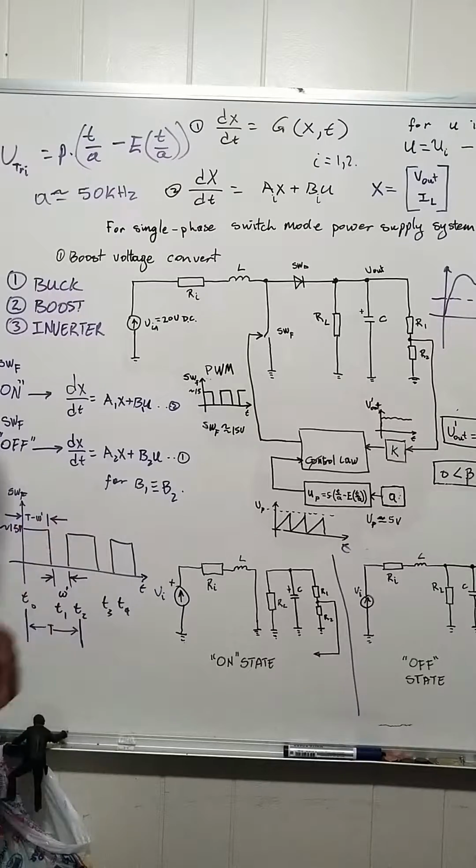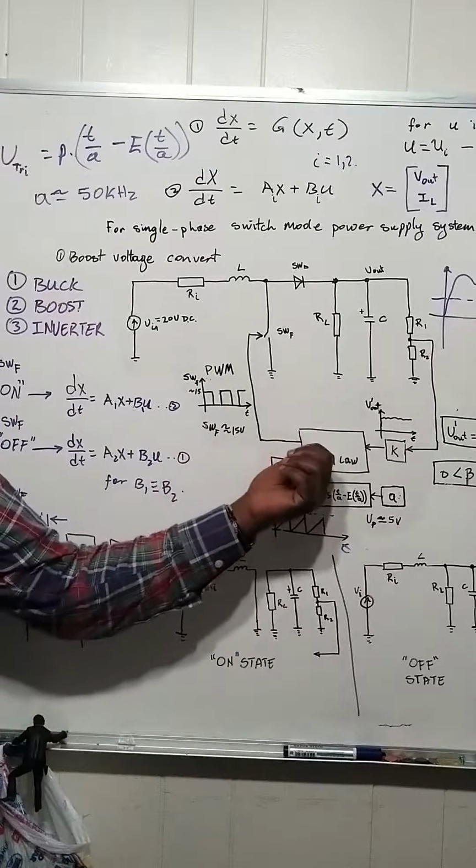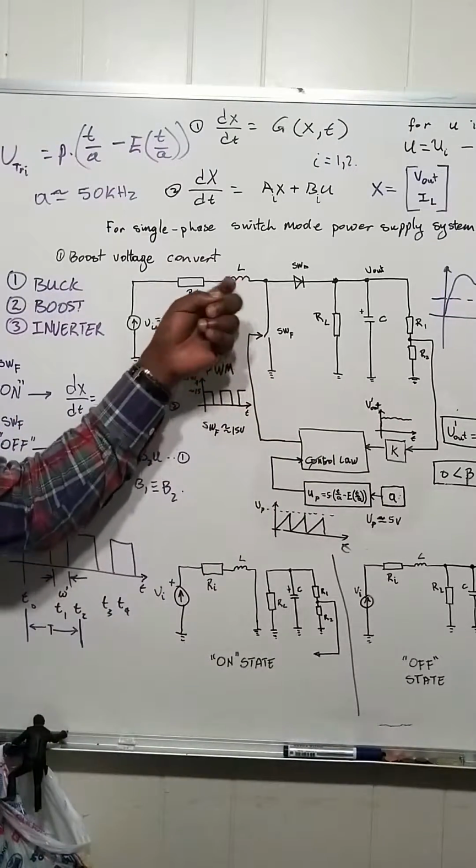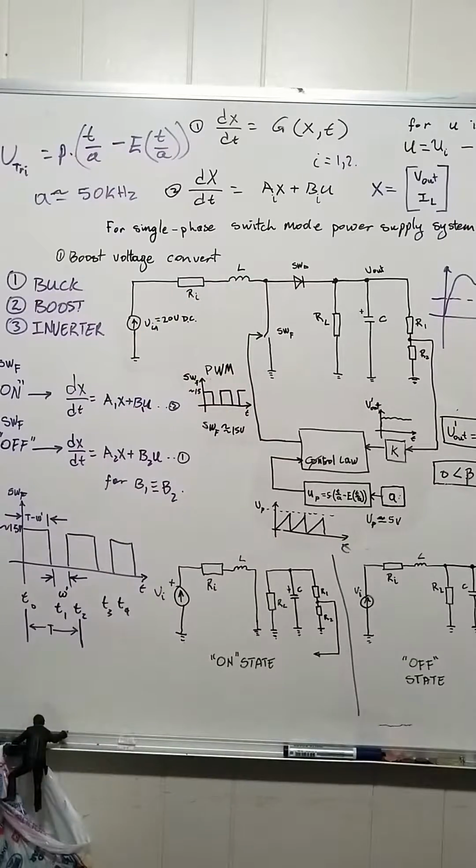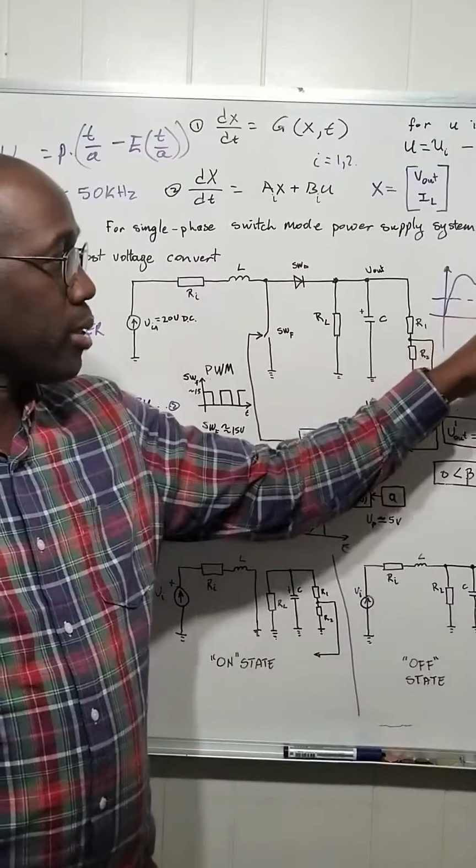What else? Here, now we need to look at the switching property, which is the pulse modulated. This shows the difference between the pulses. These are never the same. With the PWM, they always vary, because it mimics what goes on with the feedback because of the changes within the inductor. So it is not as smooth as it may look here.